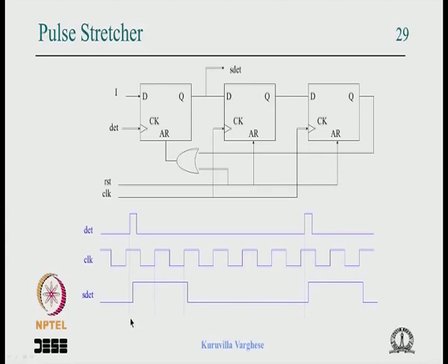Okay. So between the pulses you will get a kind of square wave, and at the state machine, when it goes high we will convert it into a pulse in terms of the clock frequency of the state machine. Which could be decided by some other input. Maybe this input is very low frequency, and there is some other input of higher frequency that will decide the clock frequency of the state machine, and using that, the signal going high will be converted in the FSM to another pulse which is wide enough to be detected by the state machine. Okay. That is the game.